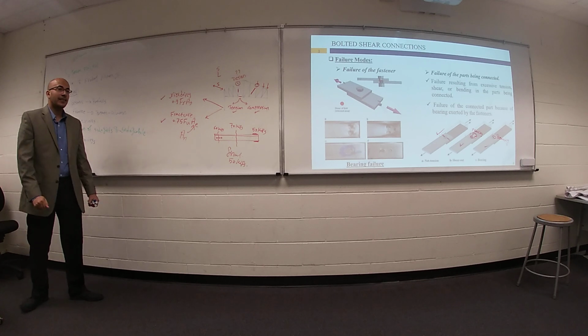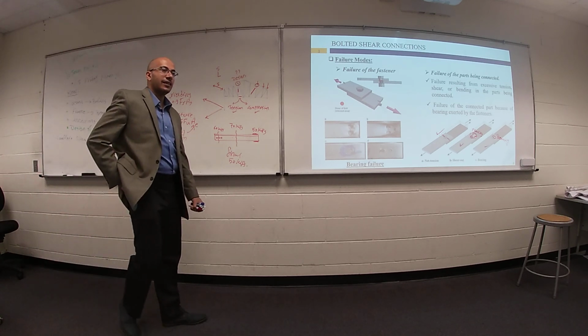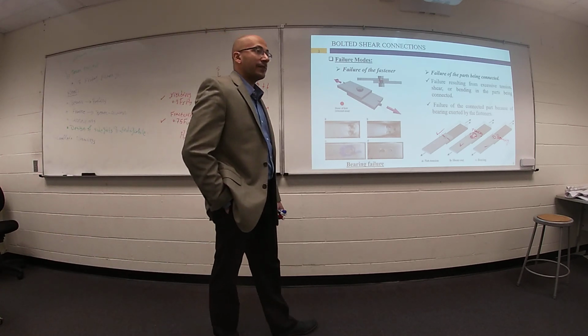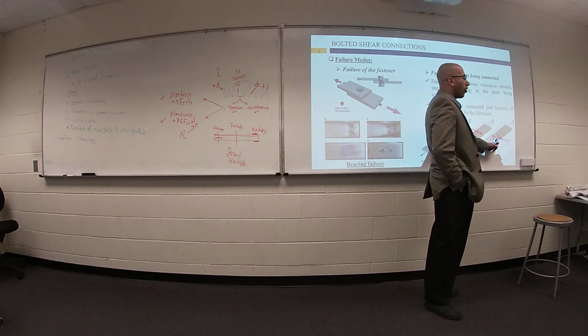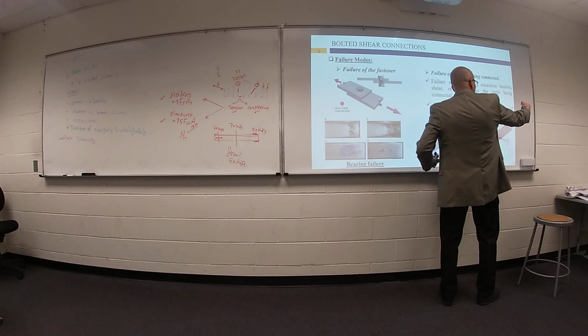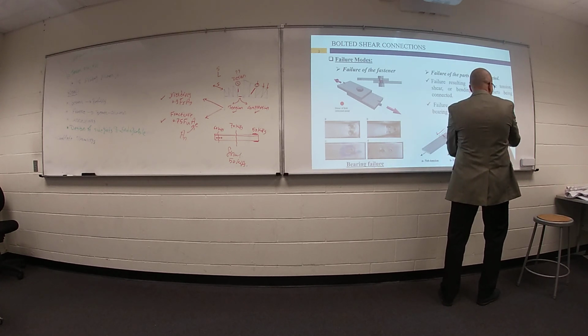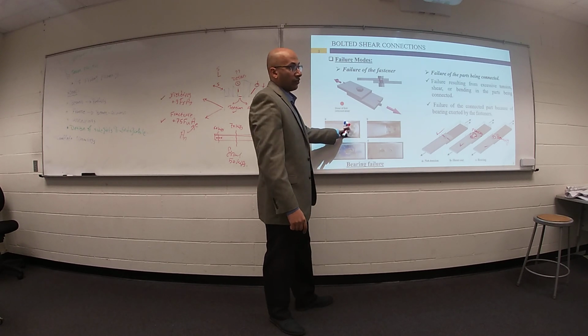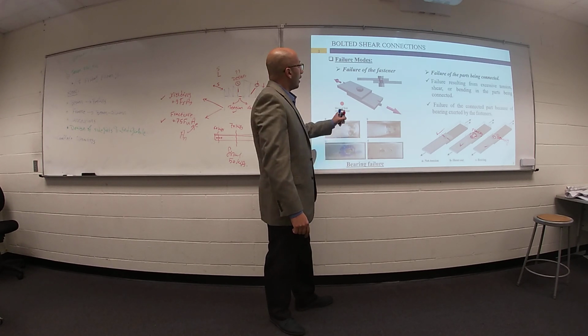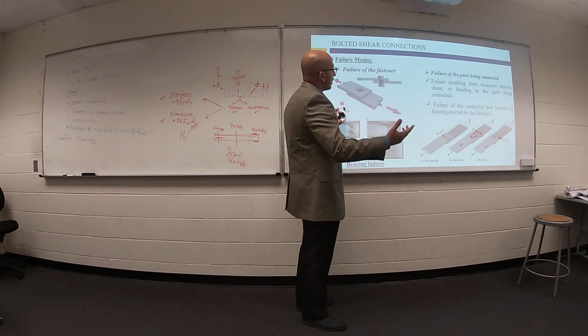All these modes of failure are due to tension. Is there any type of failure due to compression? You can expect also bearing and compression. It doesn't matter whether your member is coming in this direction or this direction. You can expect this type of failure, excessive deformation on the hole. That's right. For tension or compression, it's okay.